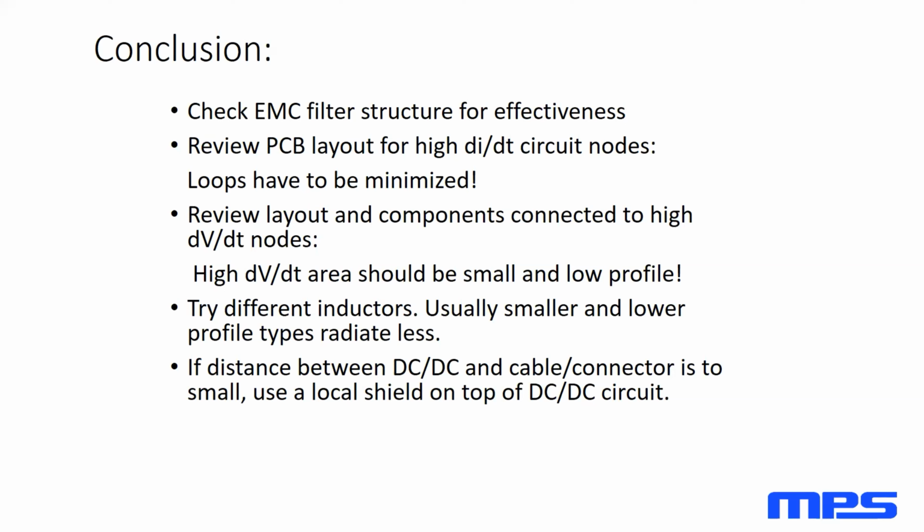They can't avoid that coupling from the switch node back to the input side, so they have to basically contain it with a shield in the design. And this particular customer says that shields are cheap and they use them on everything. So it just depends on the product you're building and what your issues are.